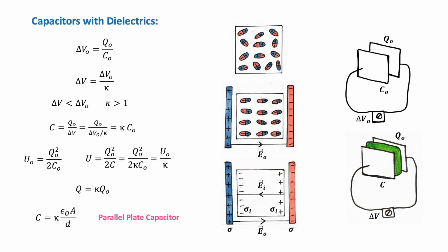So there are many types of capacitors. Commercial capacitors come in different forms and many are built into integrated circuit chips. A tubular capacitor, for example, is made using layers of metal foil interlaced with a dielectric and rolled into a cylinder. Another capacitor type consists of parallel plates separated by an insulating oil.